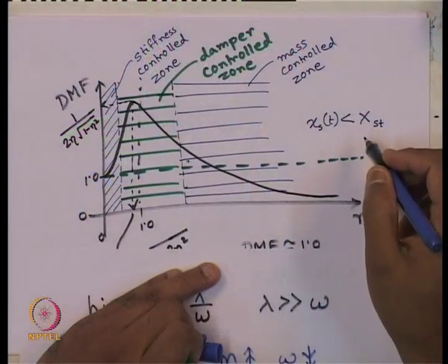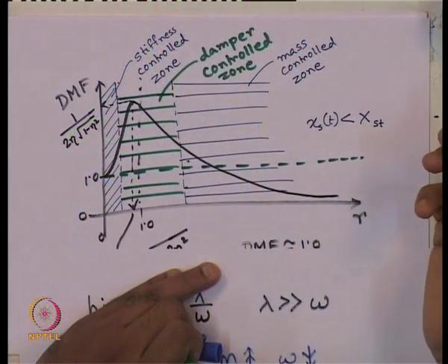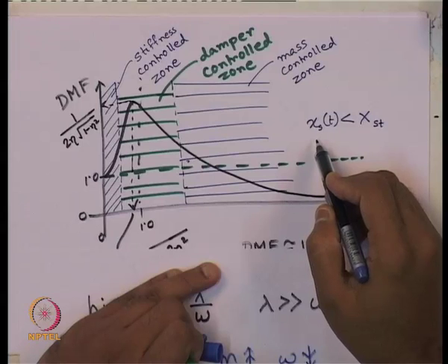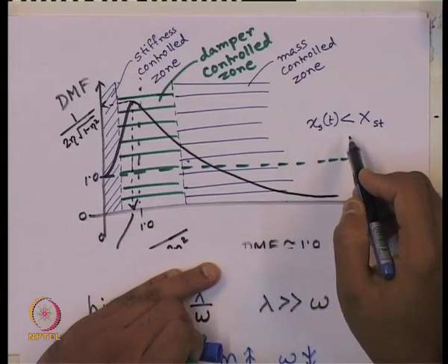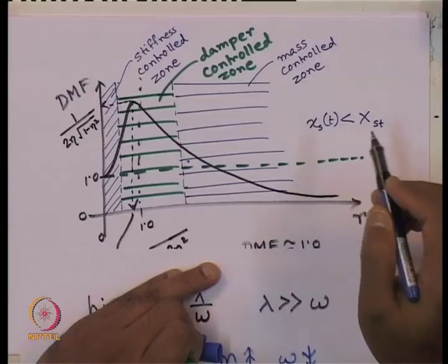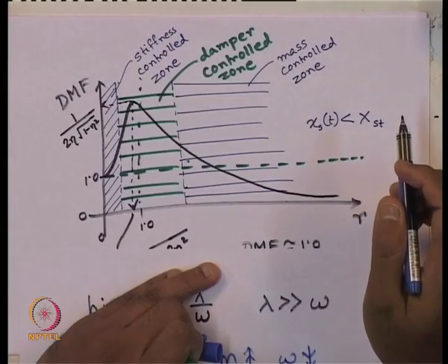Correct? Because the maximum displacement it is going to experience is the static displacement, as its dynamic steady state displacement is much less than that. So, for that kind of foundation, if we have designed it properly to take care of static load, that is good enough for taking care of the dynamic load. So, we need not design it specially for the dynamic load.